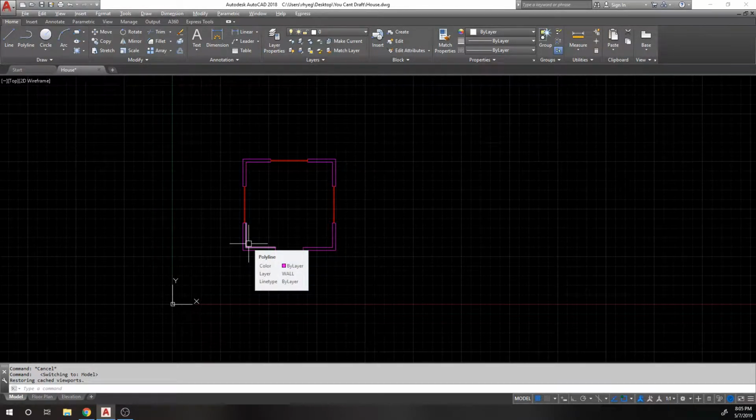There are what are called scale factors. To figure out a scale factor, you need to take 12 and divide it by the scale, which in this case is 3/8. Okay, so you can actually do a little formula in a calculator. And AutoCAD has a built-in calculator. Type in cal, and you can say 12 divided by, and in parentheses 3/8, and the answer you're going to get is 32. Because 3/8 is 0.375. So if I repeat that, it's 12 divided by 0.375, which is 32.